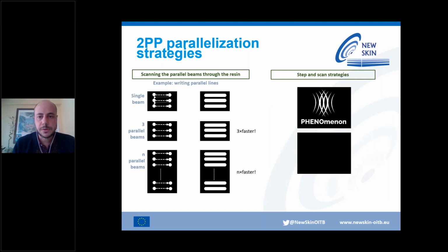There is another possibility, which is the use of dynamic optics. As I said before, if you want to replicate something like this logo, you can split it into, for example, four pieces. Go to the first quadrant, flash it with the first shape, go to the second, flash it with the second shape, to the third one, to the fourth one. By flashing different images, you can produce an overall image with any shape that you want to plot inside your resist.